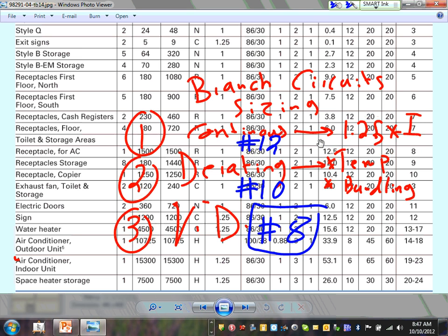Can I get you guys to understand these three things? Really, everything that I talked about revolves around these three things. We haven't done the voltage drop calculation. We will be doing it. What we did today is these two. So when you size based on continuous load or the rating, you choose the one that gets you the largest conductor. Any comments, guys? Any questions?